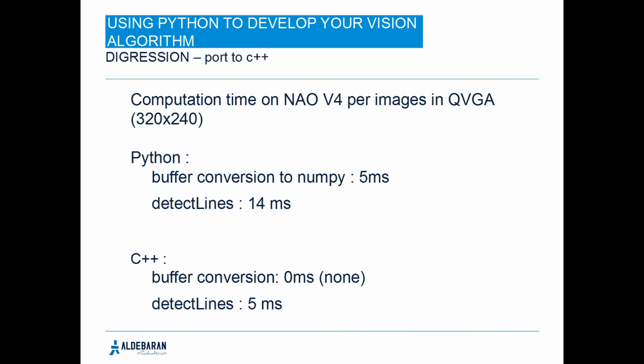As the results show, we are 4 times slower in Python. Hopefully we haven't worked at the pixel per pixel level, or it would be 20 times slower or worse. For this kind of behavior, the loss of time isn't really a problem, as the OmniWalk method can't be refreshed faster than 400 milliseconds, so it was the right choice to use Python. About developing time, developing the vision extractor in Python took me less than 2 hours, but just to port the module to C++ took more than 4 hours. And because it was already fine-tuned, 2 compilations were enough to have it working correctly on my NAO. But if we had to create it from scratch in C++, I think we would need roughly 2 days or more. So it was really the right choice to use Python.